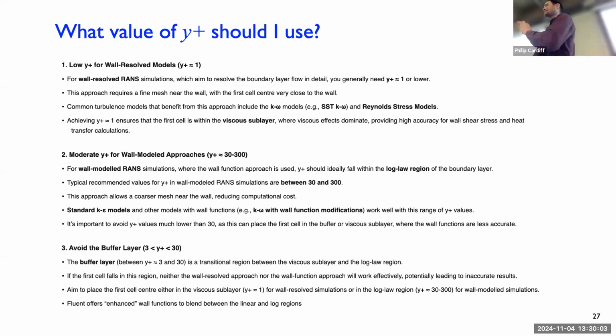To comment on the wall function as well, they're designed assuming this profile, this universal profile. That universal profile is only visible on a nice turbulent flow over a flat plate. In reality, if you're looking at a motorbike in the back of the helmet and you get a detachment of flow and a reversal of flow, that wall function just makes no sense. So wall functions really only are good estimates if most of your flow is attached and similar to the conditions for which wall functions were designed. The alternative then is you have to resolve the boundary layer. If you resolve the boundary layer, then you don't have to worry about detachment or conditions that do not follow the law of the wall.